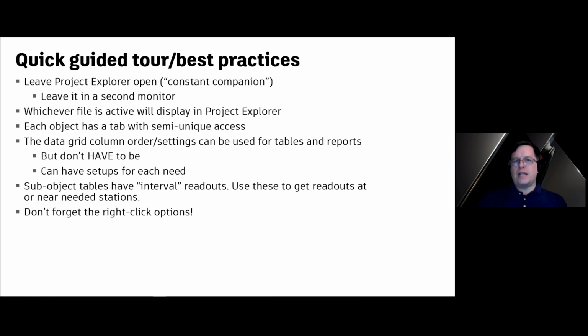Then some of the tabs that you're going to look at will have a thing called an interval readout. Now, not all tabs have this, but some of the tabs have like alignments and profiles that are very station-based. Pipes is where I like to use this particular tool. The interval will tell you where you are along a certain object, and so you can kind of, in your mind, measure out where you are in terms of your project, give you the context of where your objects are.